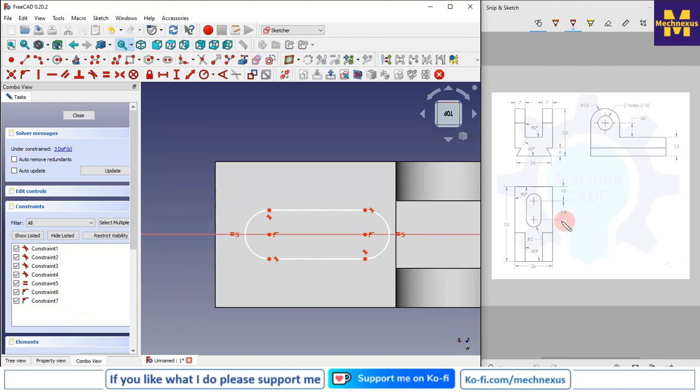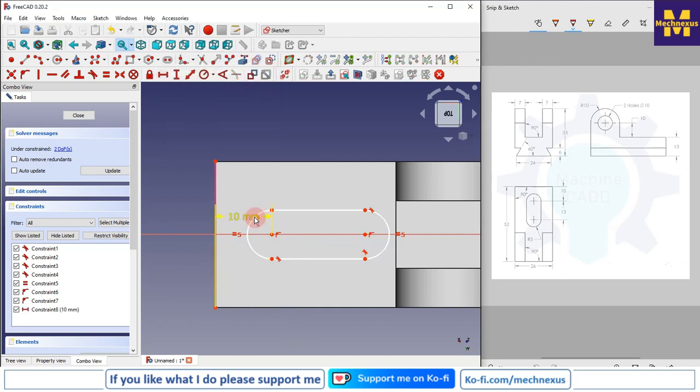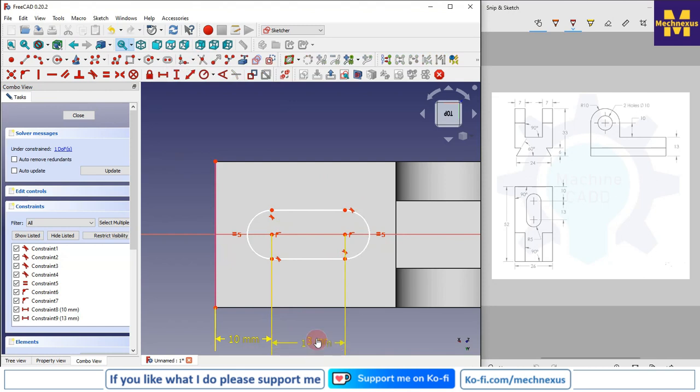And now we need to project this edge, so I will project it, and from this edge to the center horizontal dimension I will give 10, and from center to center it is 13, and radius is 5, so I will select this and give the radius 5.